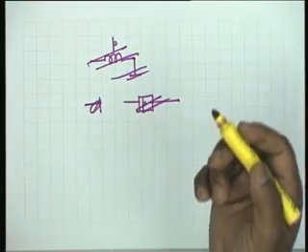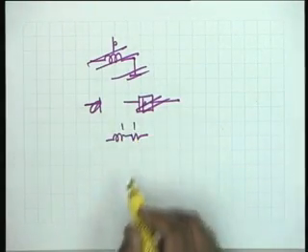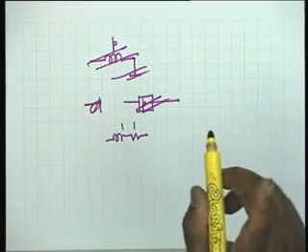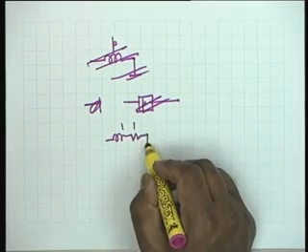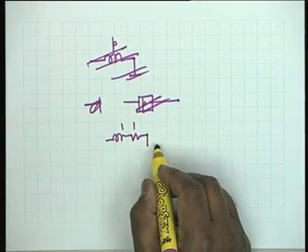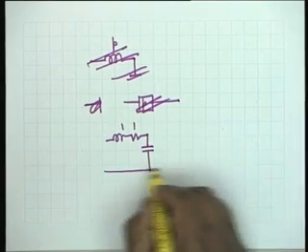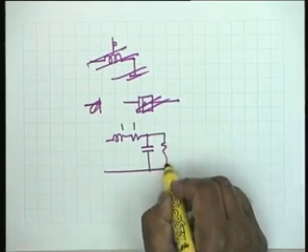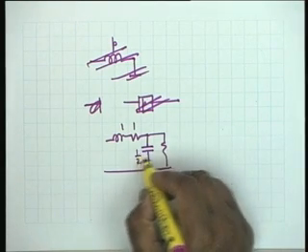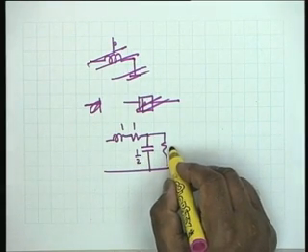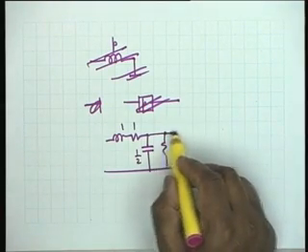You see, I need an impedance p which is s plus 1. So, I get 1 and 1, s plus 1. Then I need an admittance of p by 2 which is (s plus 1) by 2. So, I get a parallel combination of a capacitor and a resistance. Tell me what is the value? Half and 2, not 1. Okay. The next one is 4p.